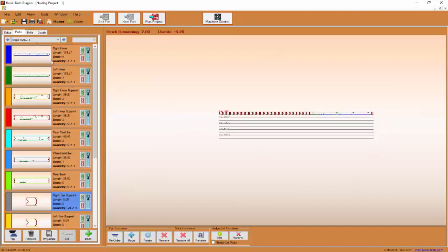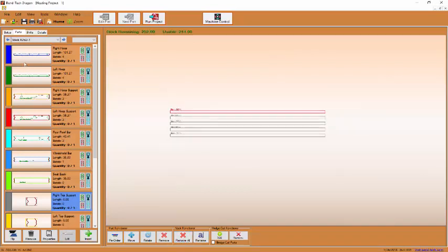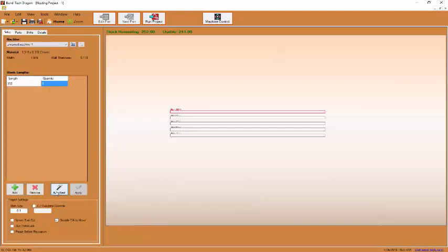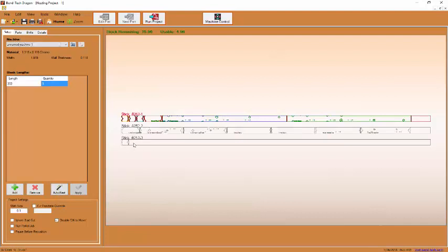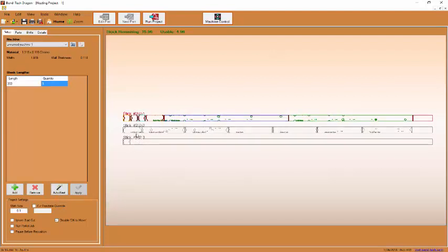Now back to what I wanted to show you before. Let me remove all the parts from the stick. Let's just say we have 5 blank sticks and all these parts for this roll cage. In the setup tab, I can click auto nest, and it tells me I only need 3 sticks, and it lines them up in this fashion. You see how it puts the short parts here, long parts here. And this part is well over 14 inches long, so the dead zone is irrelevant.